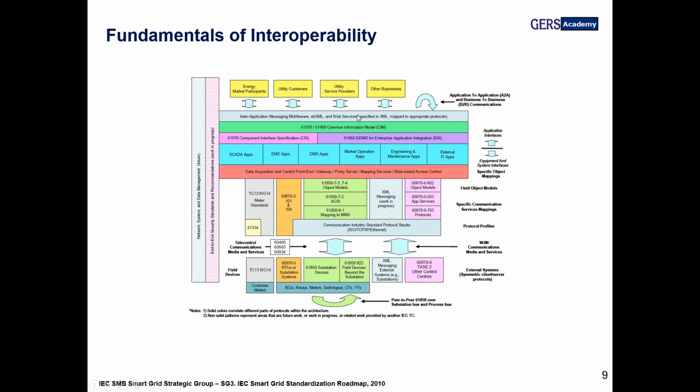We can see that we can increase the level, and starting here, we get how we could have interoperability on the substation where the IED devices are able to communicate between them, and it allows implementing some automation schemes based on their information. To date, for example, the application-based standard is IEC 61850, and it has allowed implementing many applications like the digital substations.